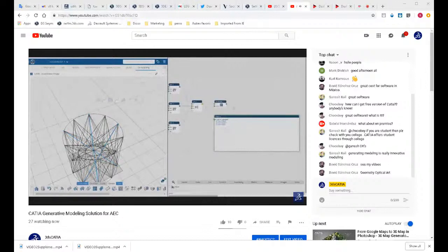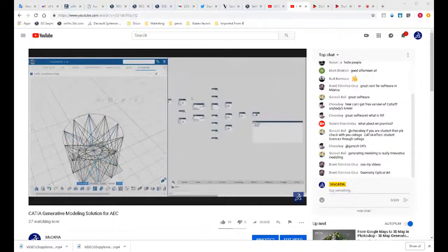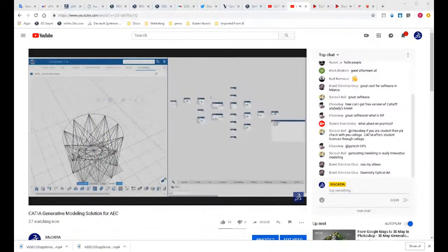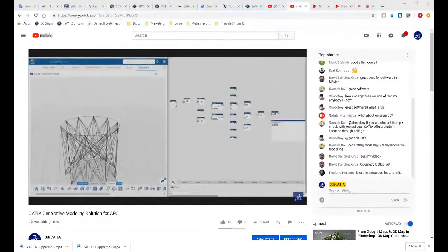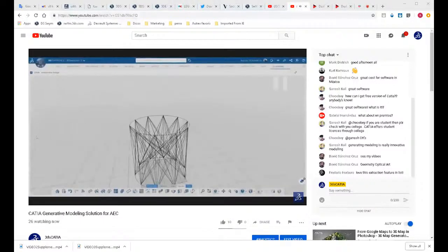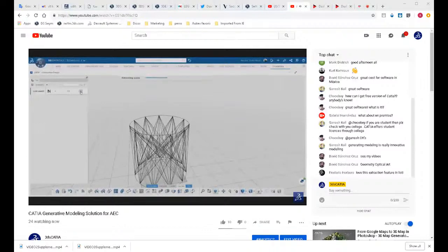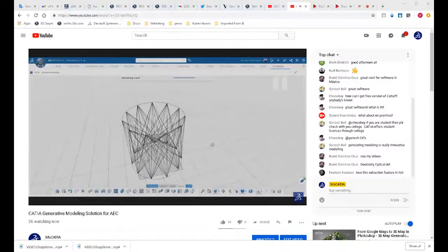This is probably the most efficient means to work with a lot of geometry, and when you need to find a hierarchy between elements, the best way to manage lists will be the graph in that case. But once your logic is done, you can shift to the immersive interface and start working and doing some versions, some optioning directly from the immersive. So here I am going to change the divide number directly from the immersive, and you can see that it has updated with the graph being closed.